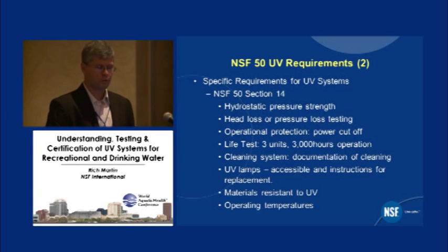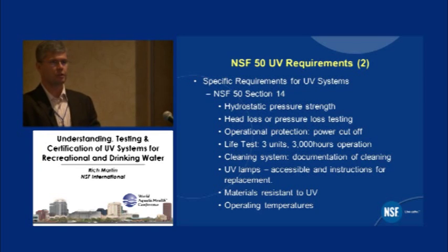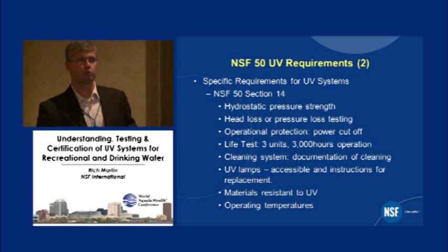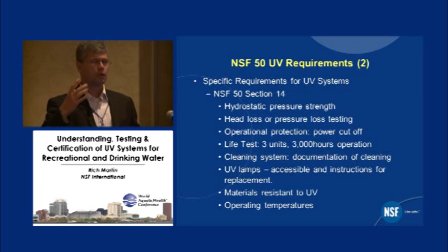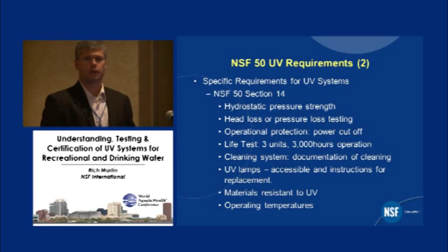Beyond that, there's what we would call the operational protection, and that's a methodology to make sure that the users and personnel at the water facility aren't going to be exposed to the ultraviolet light radiation, so there's power cut systems such that if you try to remove the lamp from the system, it won't create a risk to the operators or users.